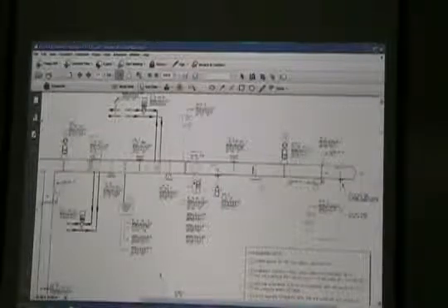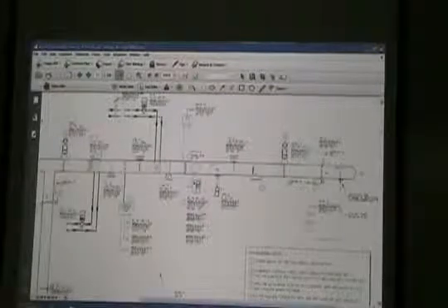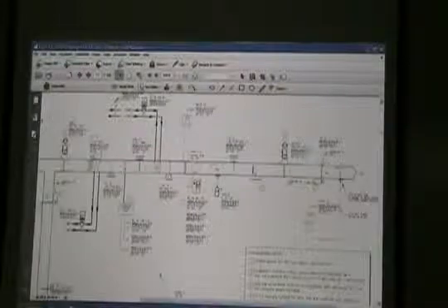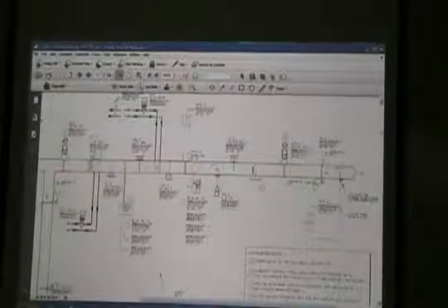On the air handling unit graphic, provide a button entitled Critical Zone Reset Override. If this button is activated, then the supply fan should be modulated by the variable frequency drive to maintain supply static pressure at 1 inch. That just gives the operator the opportunity to do away with everything we talked about last week as far as resetting boxes. He's going to try to maintain 1 inch all the time.